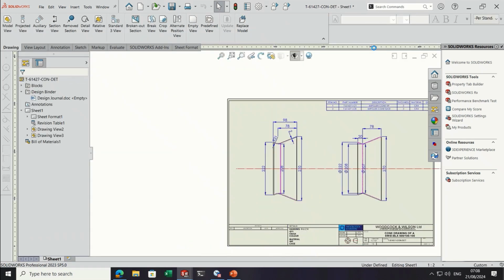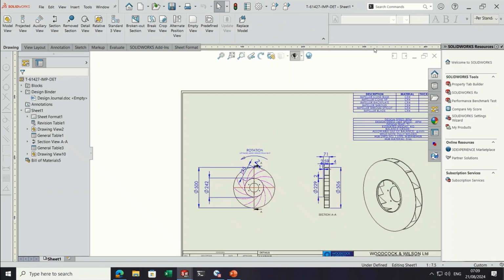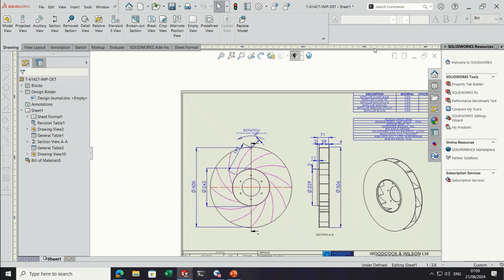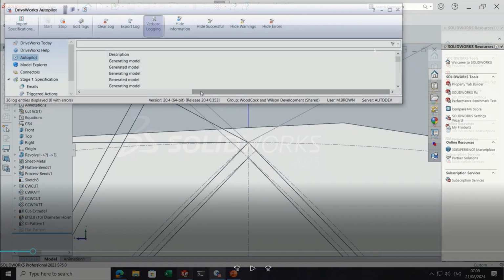After this stage, then post-generation tasks can be run on the child, and triggers can be used to order and sequence other tasks, such as pack and go, sending emails to customers, and moving dimensions on drawings.